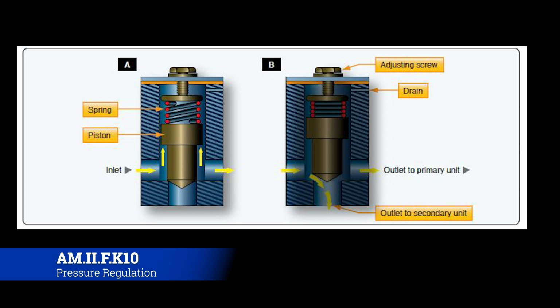And you'll see these all over the place. That's in terms of hydraulic sequence valves, but this same sort of setup will happen all over the place. There'll be a small adjusting screw that you have to turn to change the pressure or the flow rate or something on any sort of device that has fluid flowing through it. This just happens to be in a sequence valve.